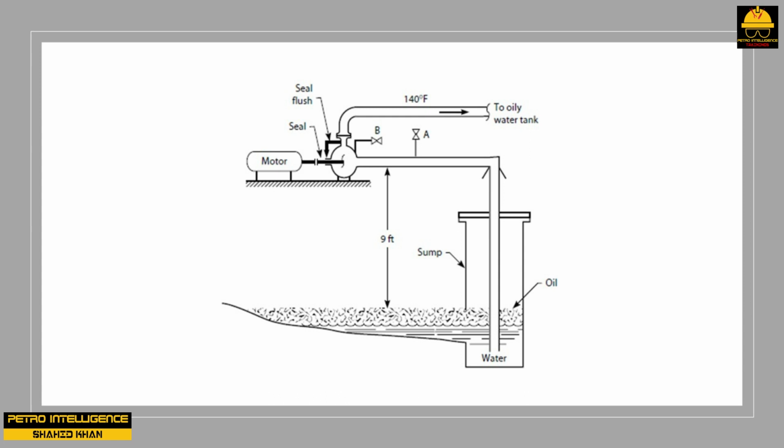The problem with priming the pump shown in the picture is that the water needed to fill the pump's case, that is, to prime the pump, is below the pump itself. Certainly, there are self-priming pumps. These pumps are designed to compress very, very small volumes of air, and to produce very, very small discharge pressures with the air. The circulation pump on my swimming pool is of this type. After running 15 minutes or so, it draws through itself a few cubic feet of air before it can pick up suction. Most high-head, large volume pumps must be primed with an external source of water.